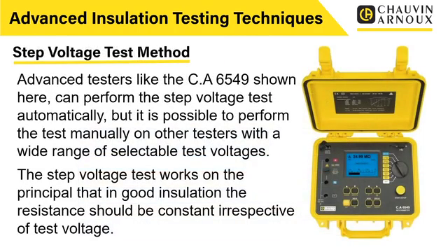Now, the next test we're going to look at is slightly different. This is the step voltage test method. Advanced testers like the CA6549 shown here can perform the step voltage test automatically. But it is possible to perform this test manually on other testers with a wide range of selectable test voltages.